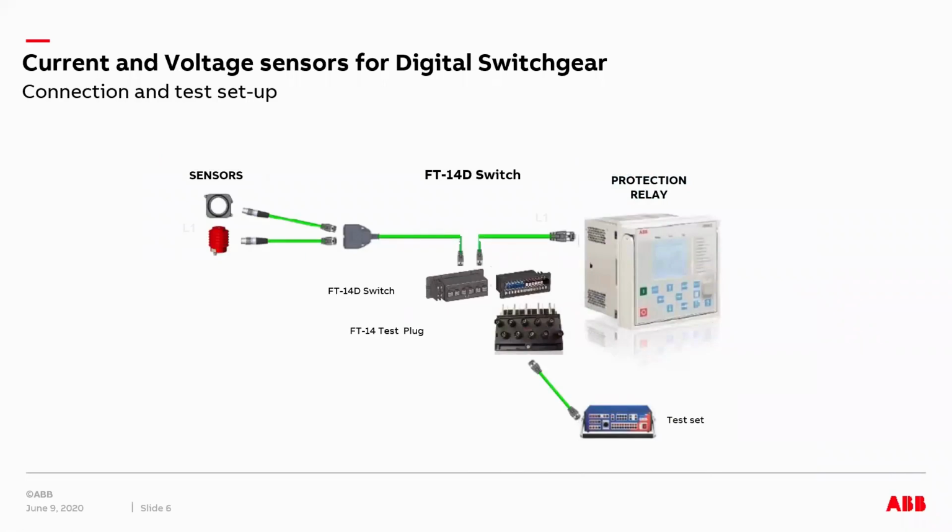So what is a low energy analog input? These low energy analog devices are the devices popularly known as sensors. So you have the picture of sensors here. These sensors are used to replace the traditional CT and the PT. Here is the picture of a current sensor. It's based on the Rogowski coil principle, and this current sensor brings out a millivolt signal on this Ethernet cable here.